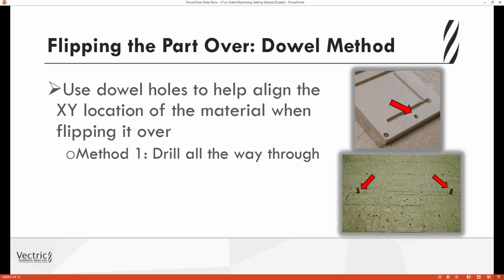Now there's two ways to approach this. So method one is to drill all the way through your material and straight into your spoil board.